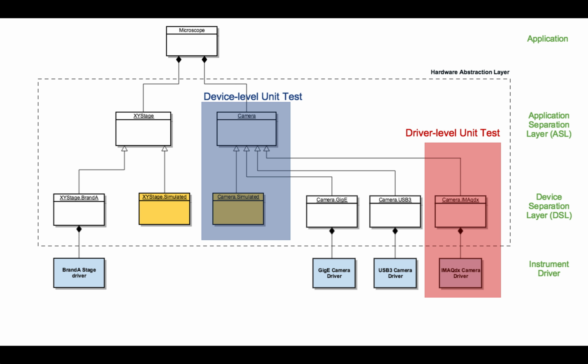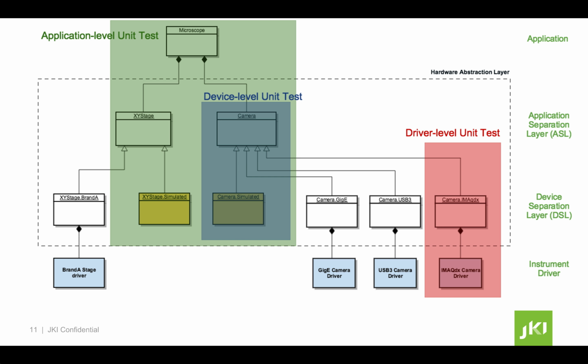Now, the next test is to do a driver level unit test for each of your modules that will be swapped for a camera simulated. And obviously these two tests can be combined once you do a system level test where you have a camera with actual hardware connected. So using your favorite unit test framework, either the NI unit test framework, JKI's VI Tester, or Caraya, you can develop good, solid, reproducible unit tests here.